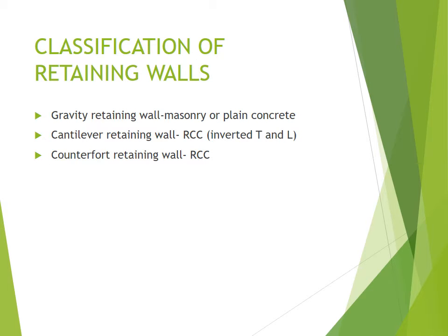So gravity retaining walls require greater toe to provide sufficient base width so that no tension is developed at the base. Also, a very heavy section of stem is required. So you can see we have the toe and the heel at the bottom, then the stem, which is now the wall, and the face, whereby now the wall is facing the side of the sea or the ocean, and the back, whereby we have the back soil.